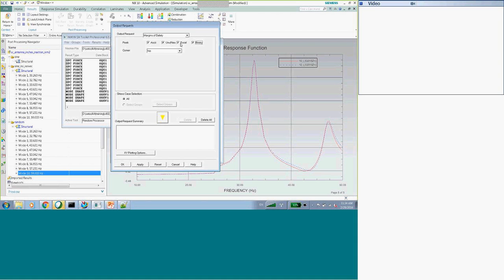So margins of safety, of course. I'm putting them in the binary file. Then I'm going to define failure metrics. I'm going to put them in the binary file. I'm not going to use them, there are none for 2D ply elements. My safety factor, put a factor of 2.